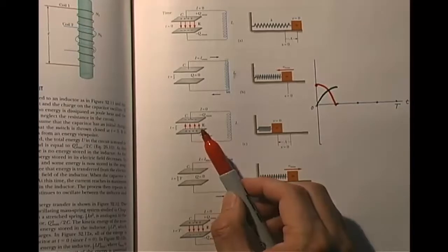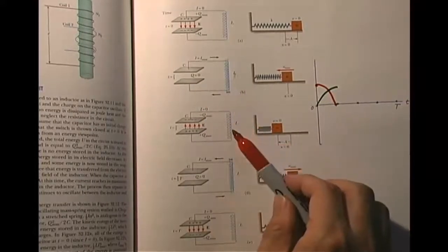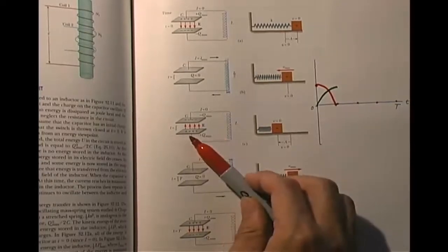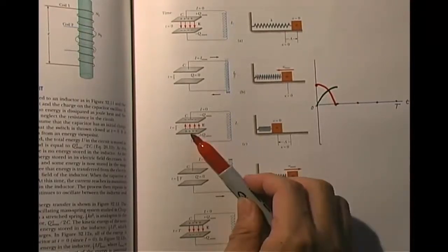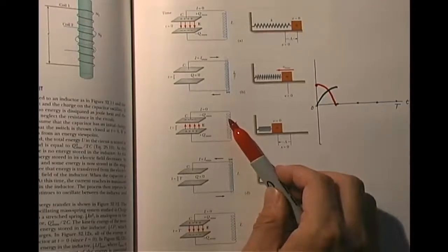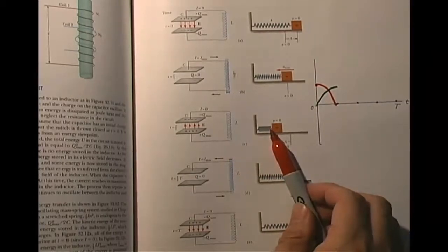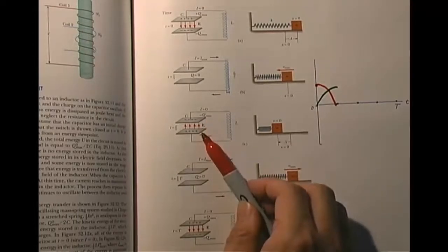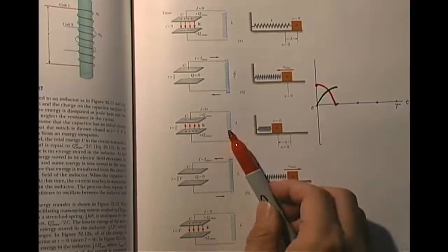Similarly, in the electromagnetic case, you start with no charge, or no electric energy, with a lot of current, and then gradually, as the current continues to flow, more charges will be stored on this plate and that plate, so gradually you recover electrostatic energy on the capacitor, but you lose magnetic energy on the inductor in return. Now, when the spring is fully compressed, the block is not moving. Correspondingly, when the two plates are fully charged, there's no current anymore because all energies are electric, no magnetic energy, so the current is 0.